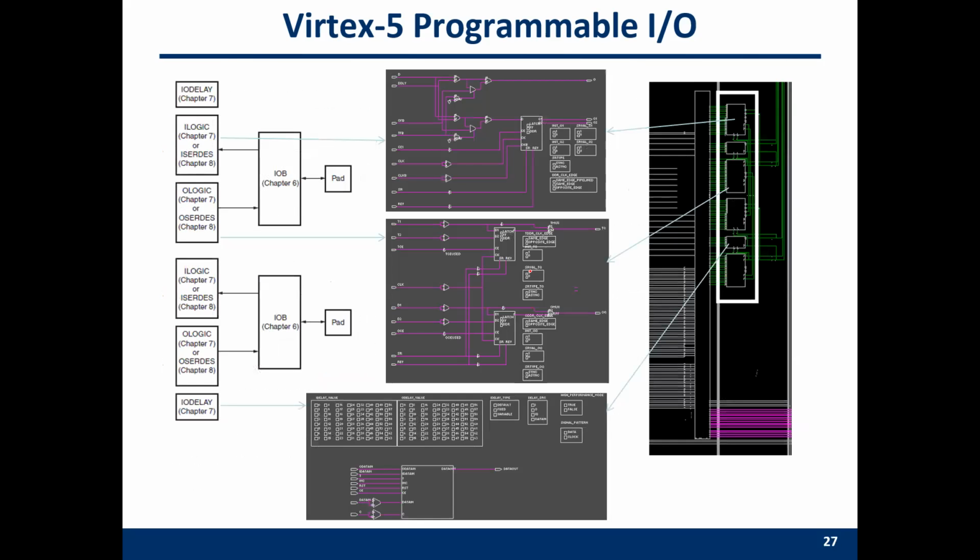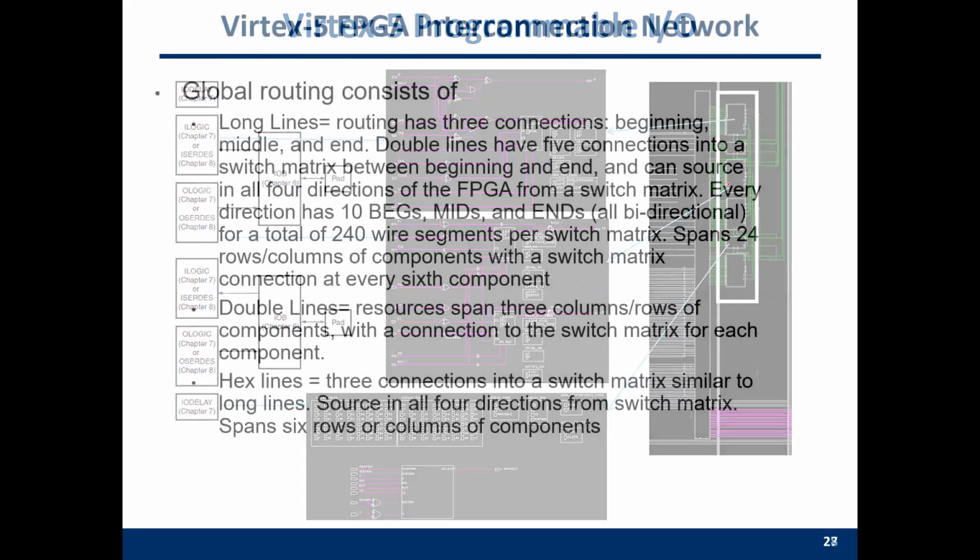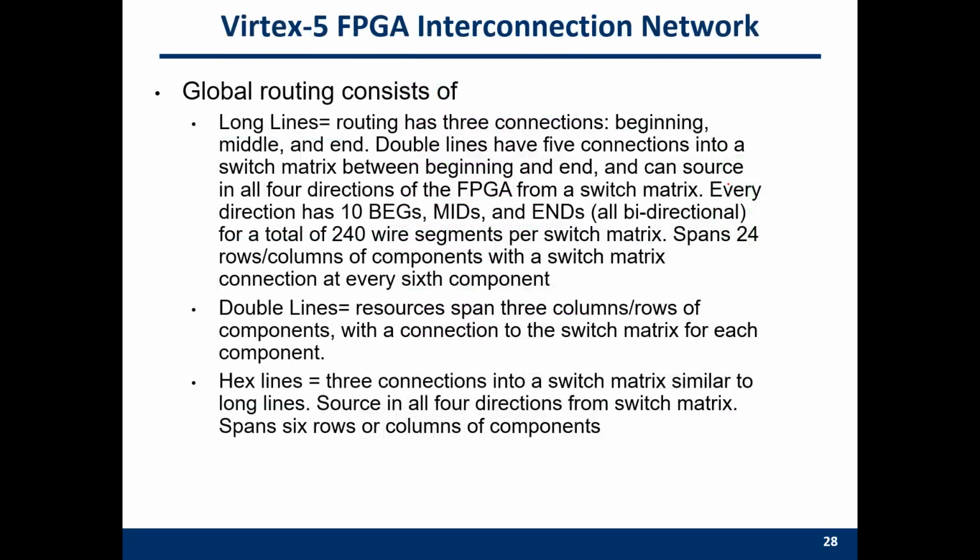And this is the layout for the I/O cell. You can see that the I/O cell here is actually much larger than one single CLB, configurable logic block. So besides the CLB and I/O cell, one FPGA board also has an interconnection network. I believe the interconnection network occupies the largest area on the FPGA board.